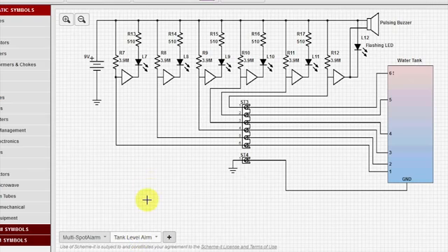This is pretty much the same circuit, rearranged slightly, and connecting the ground to the bottom of the water tank. This would let you know the level at 6 different positions, and the 6th one being a flashing LED. We sell these and they work up to, I believe it's 14 volts. And it would also turn on the buzzer letting you know this tank's about to overfill.